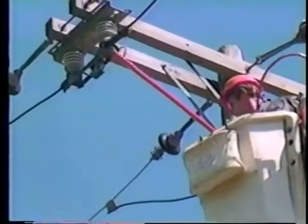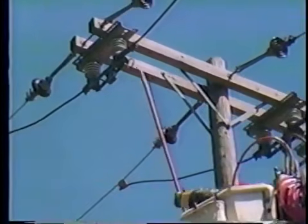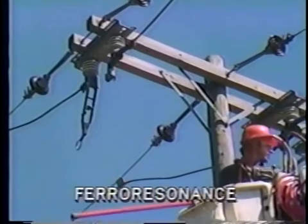All of the faults that we've been studying so far involve short circuits. There are other abnormal conditions arising from open circuits, but these are far less common. Let's look at a typical example of one phase which is open-circuited. And this case will serve to introduce the term ferroresonance. You'll remember from your study of electrical fundamentals that the term resonance refers to the combination of inductance and capacitance that can give rise to extremely high voltage levels.